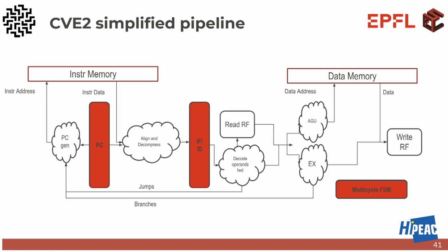So that means that if you have an instruction that requires more than 1 pipeline stage to keep a throughput equal to 1, it will stall. And it becomes a multi-cycle instruction. A typical example of this kind of operation is a load and store. Because usually, memories are implemented in SRAM, and usually SRAM replies at least 1 cycle after. So that means that if I send the address at time t, I get the answer, best case, at t+1.